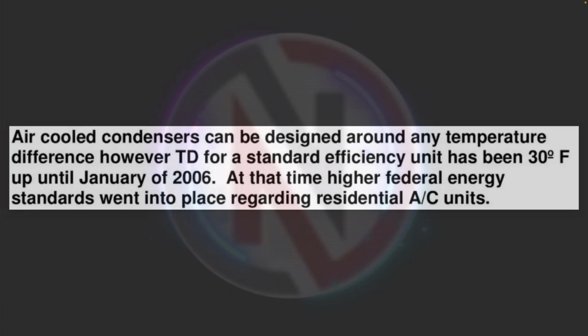Air-cooled condensers can be designed around any temperature difference. However, TD for a standard efficiency unit has been 30 degrees Fahrenheit up until January of 2006. At that time, higher federal energy standards went into place regarding residential AC units.